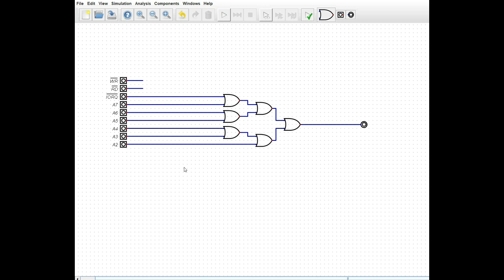We are also going to have a sound chip at port 1C. And then another video controller, either the TMS 9918 or possibly the 9958, is going to be at memory locations 14 and 15. I'm going to have a game port to read a Sega Genesis controller, and that's going to be at locations 30 and 31.